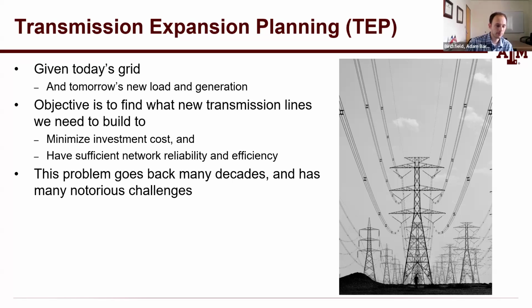Yes, that's a good question. That was one metric that we looked at, how close the generators are to their reactive power limits, and so how much extra reactive power we have available in the system. And that's also reflected in N-1 contingency analysis, where we look at whether there's enough reactive power not only for the base case but also for the contingency conditions. There's a variety of ways to quantify the reactive power sufficiency, but we did look at a couple of things in that area.